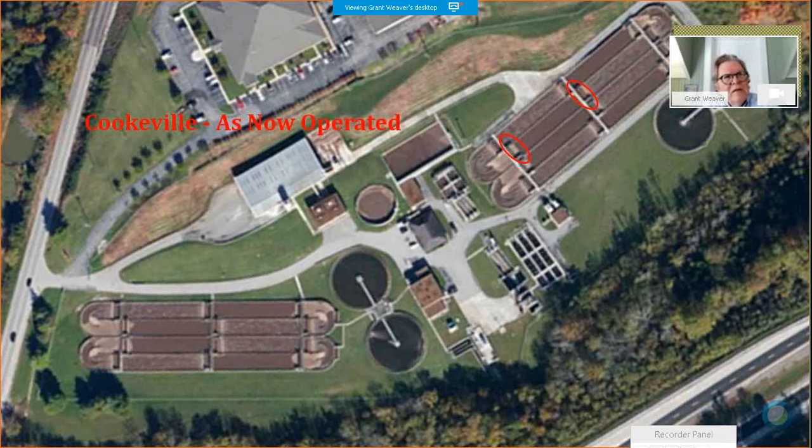Some of the phosphorus-removing bacteria that are in and with the mixed liquor are falling into that sludge blanket. They're eating those volatile fatty acids. When that zone gets resuspended, it becomes aerobic, and they're getting phosphorus removal. All right? And I think what we saw from that graph is they're beginning to see a more consistent number year-round and starting to dial it in.